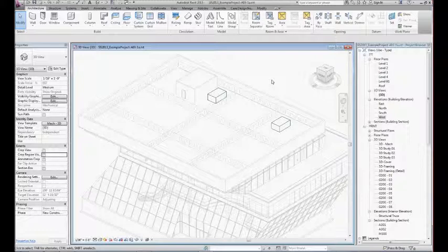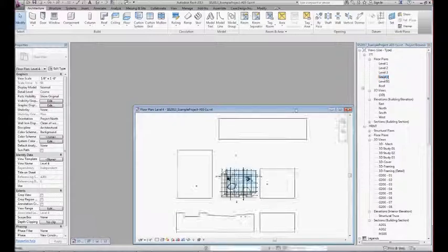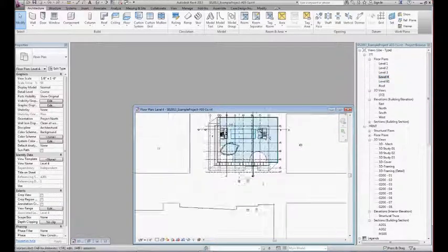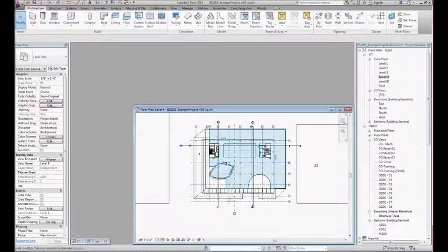You would think you could get around this using a 3D view, like the one that we have here, but unfortunately in this sense the 3D view behaves like a plan view, so we can only model horizontal duct here. So what I like to do to get around that is I'll take a floor plan. So I've got level 4, and I'm going to get a nice vertical view. In this case I'll do my south elevation because it lets me see both of my cores.